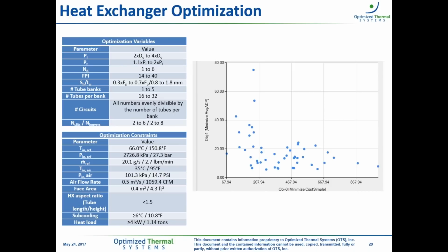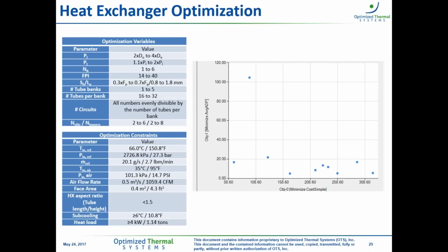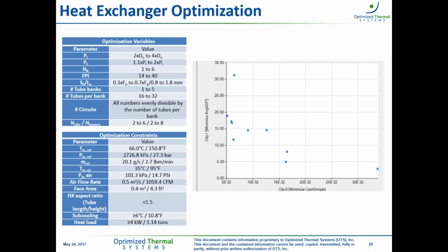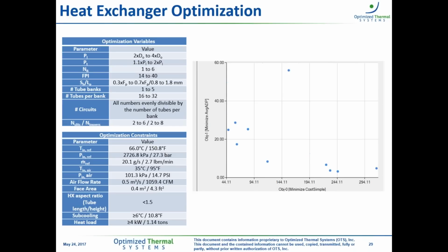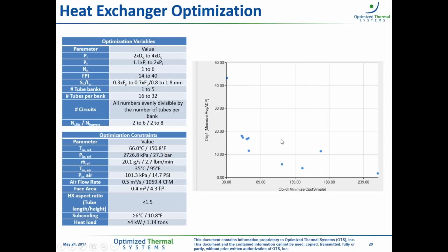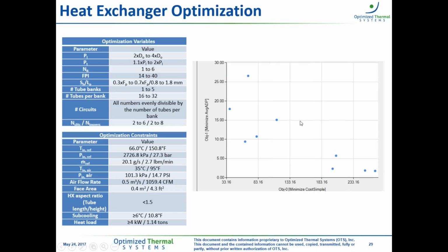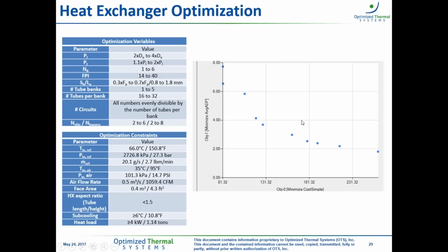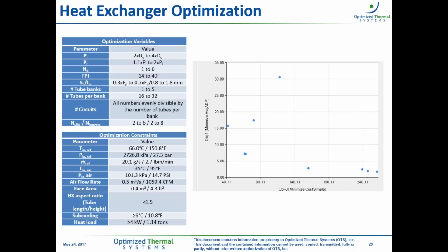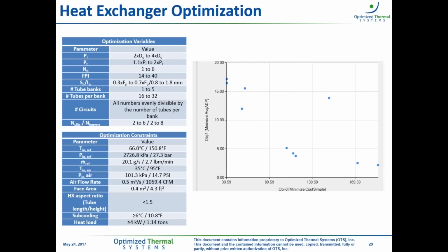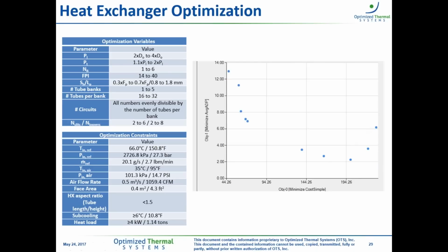And what we did with this problem definition is apply a multi-objective genetic algorithm solver to solve this problem for us, using heat exchanger modeling software to predict the performance of each candidate design. Just as a graphic, I'm showing on the right-hand side a visualization of what that process might look like if we look at a genetic algorithm solve a problem through each iteration as it learns from one to the other how different design parameters affect the performance of a heat exchanger.